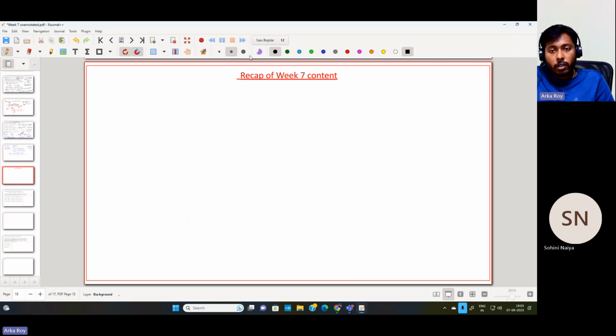We have to design an equivalent analog filter over there, and then from the analog domain, remap that analog filter response to the digital domain filter response.